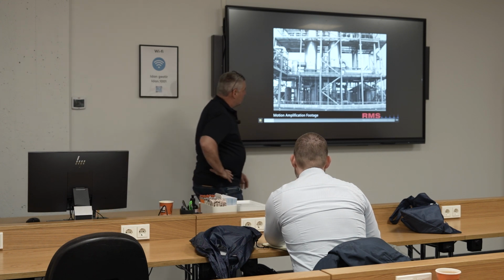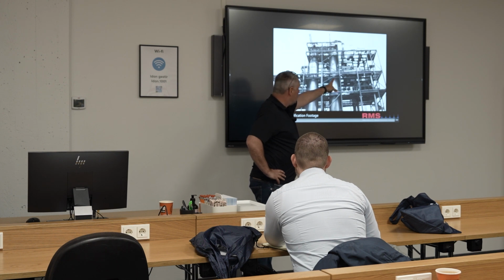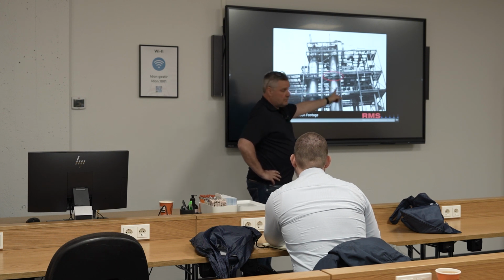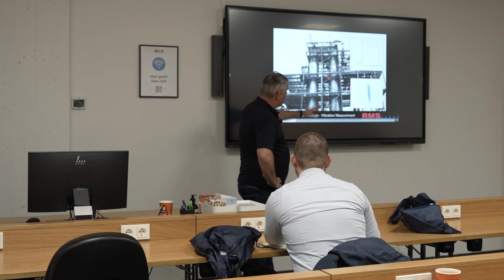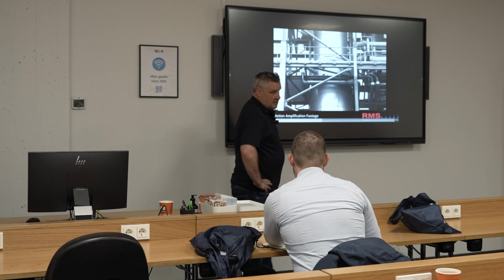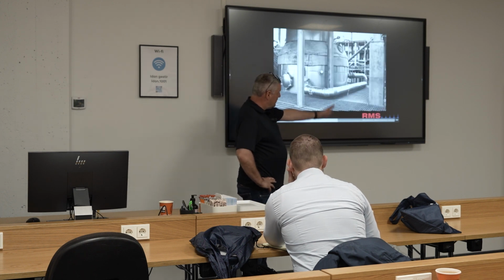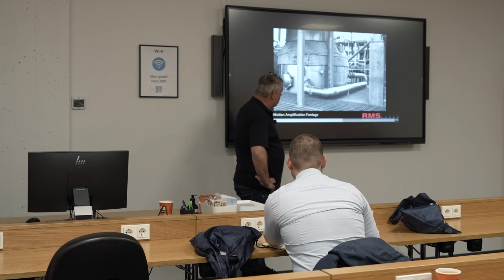So this is amplified footage just of a structure, and then you can home into certain little areas that are vibrating as opposed to others, you know. From a good field of view, you can take a measurement there, you can get a spectrum, you can get the XY plot, all from afar. Whereby before you'd be hunting around with an accelerometer for days. You know, it's really valuable for that type of situation. You can see the difference between the standard footage and the amplified. So it's nice to show.